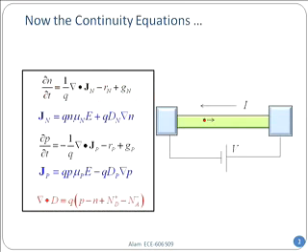Now, as I have mentioned several times before, there are these 5 equations. In fact, 3 equations, if you count properly. That is, the first equation is the continuity equation for electrons, and I'll explain what I mean by continuity. Then you can see that there is an expression for the current, and the second equation simply says how the current responds to electric field and density gradient.